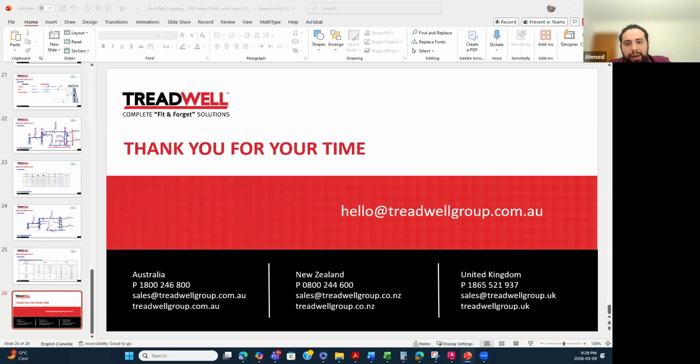I will add something. For any project we receive, we prepare a full shop drawing, including the bent parts and everything about the parts. So the parts that we send to the site include everything with the bar mark, so you don't need to bend the parts on site.